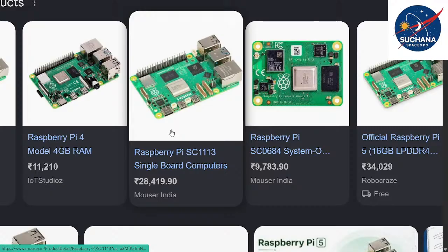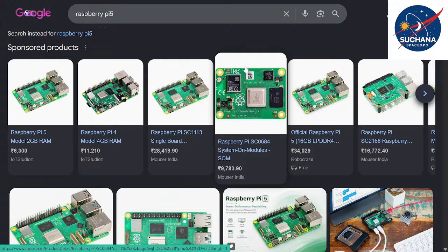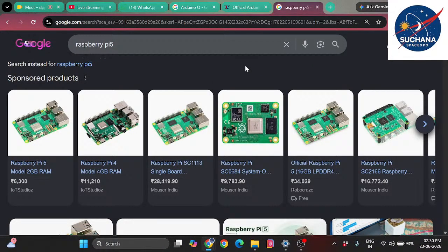We also said yesterday a few things about the ESP module, right? We discussed a few things related to the ESP module. I said that there is something called ESP8266, and another variant of ESP is ESP32. I told that ESP8266 does not have Bluetooth functionality, whereas ESP32 has Bluetooth functionality. Moreover, ESP8266 runs on a single core, whereas ESP32 runs on dual core, so it can do more tasks. It can run different kinds of tasks simultaneously. It can perform asynchronous and synchronous actions with the help of dual core.